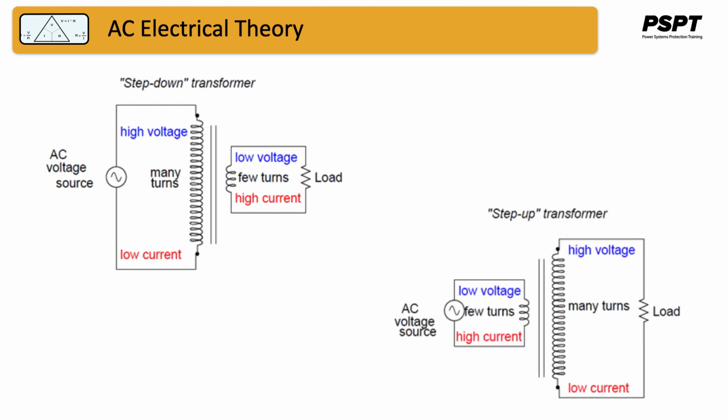The AC voltage induced in an unpowered secondary coil is equal to the AC voltage across the powered or primary coil multiplied by the ratio of the secondary coil turns to the primary coil turns. The transformer's ability to step AC voltages up or down with ease gives AC an advantage unmatched by DC in the realms of power distribution.